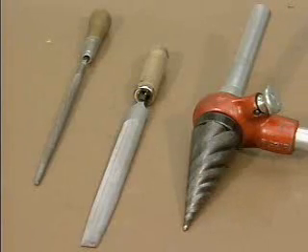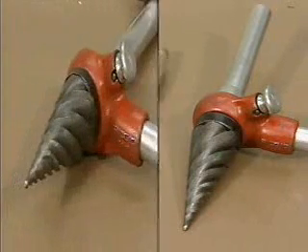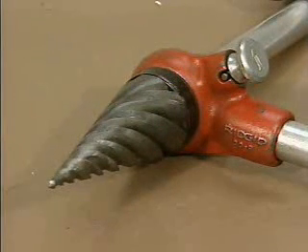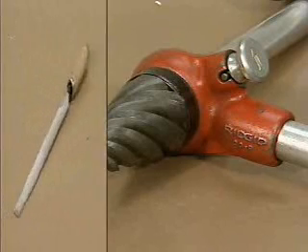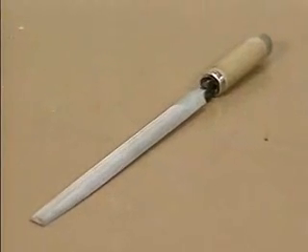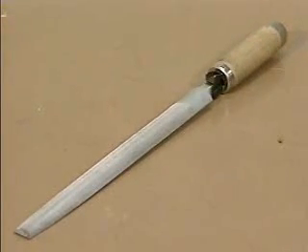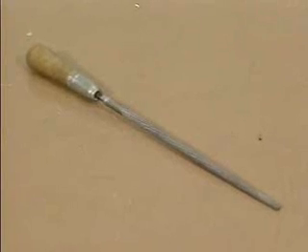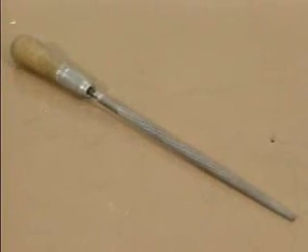Pipe reamers, half-round files, and rat-tail files can all be used to remove internal burrs and ridges. A pipe reamer, such as this one, has a cone-shaped file that can be inserted into a pipe. This is a half-round file. Its file is a circular segmental section that is tapered in thickness and in width. A rat-tail file, such as this one, has a tapered body that comes to a very small point at the end.